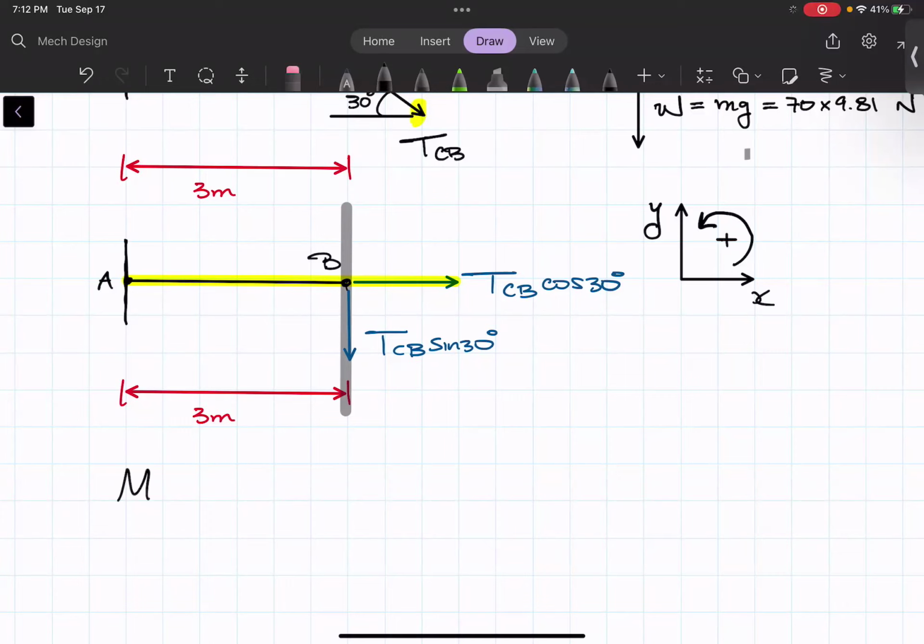So essentially, the moment about A, force distance method, is going to want to create a clockwise rotation, right? Just picture it like this. Picture AB being a stick, okay? You're holding point A with your fingers and you're pulling down at the edge of the stick, okay? What does the stick want to do? It wants to rotate clockwise, okay? And essentially that's how you want to visualize it, okay? Always visualize it conceptually, right? Always think about it from a real world application, okay?